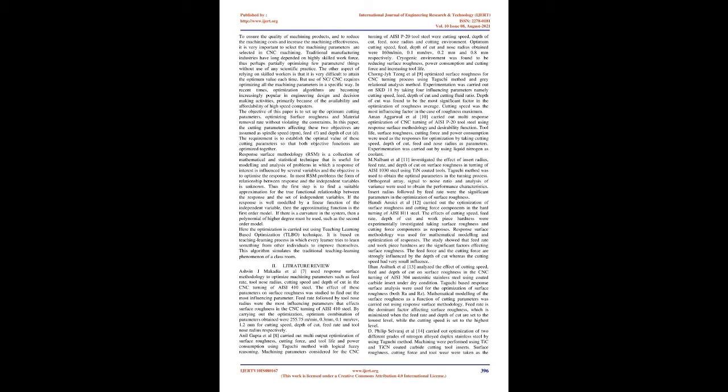The resultant roughness produced by a machining process can be thought of as the combination of two independent quantities: ideal roughness and natural roughness. Ideal surface roughness is a function of feed and geometry of the tool. It represents the best possible finish which can be obtained for a given tool shape and feed. It can be achieved only if the built-up edge, chatter and inaccuracies in the machine tool movements are eliminated completely. But in practice, it is not usually possible to achieve such conditions.